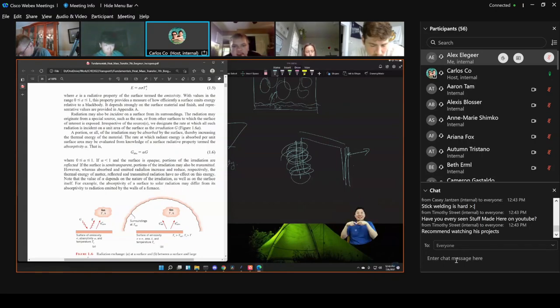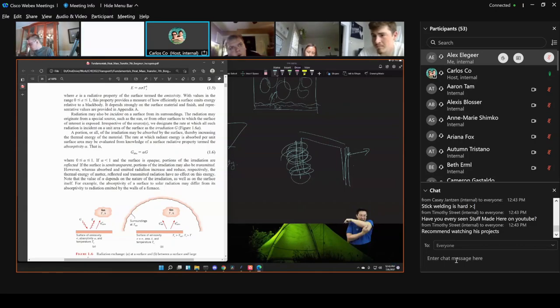Do you see how many dimensional integrations you're going to end up having to do? That gets extremely nasty. The truth is, very few engineers actually do those integrations themselves. Those things have been pre-calculated and referred to as view factors, for, let's say, a plane and a plane at different angles. They basically become just a formula to use. So I don't really bother to go into that too much.